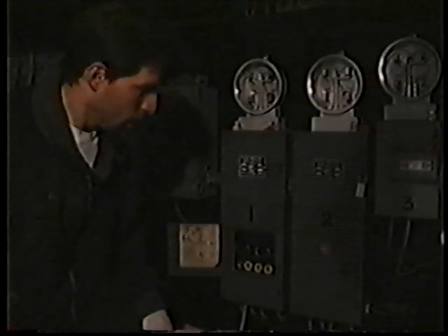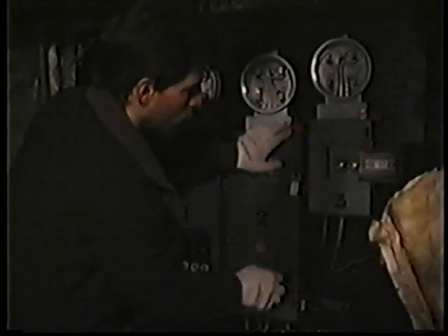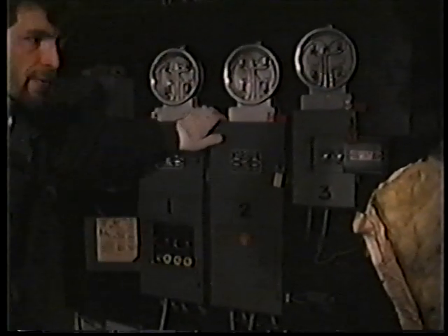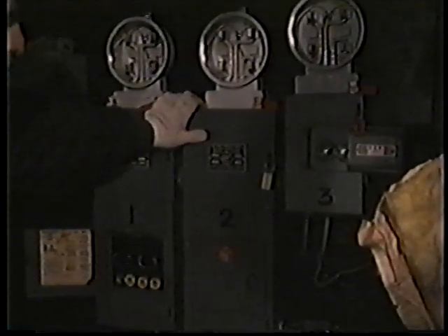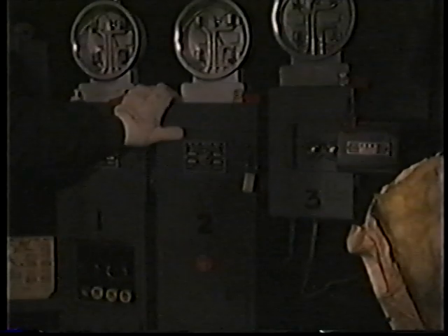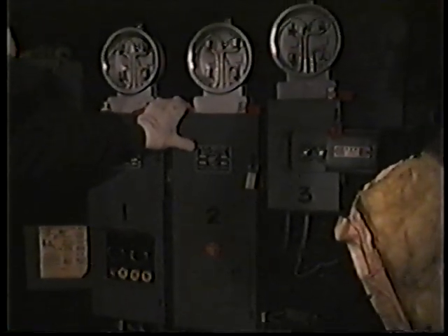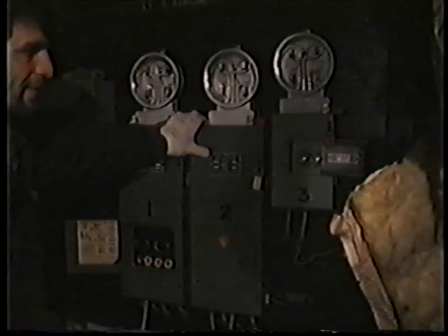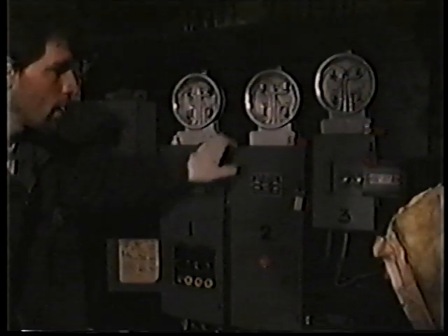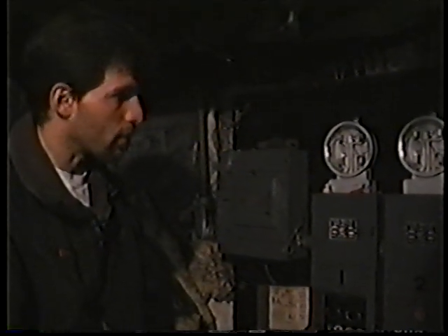But this little system here has just two fuses in it. The 3rd floor apartment here only had two circuits going up to the whole apartment, where nowadays we generally have anywhere from 8 to 10 circuits going up to an apartment, and usually about 4 or 5 of them are just in the kitchen alone. Bedrooms, we usually put one circuit up to each bedroom, and the bathrooms, 1 circuit is also required nowadays.